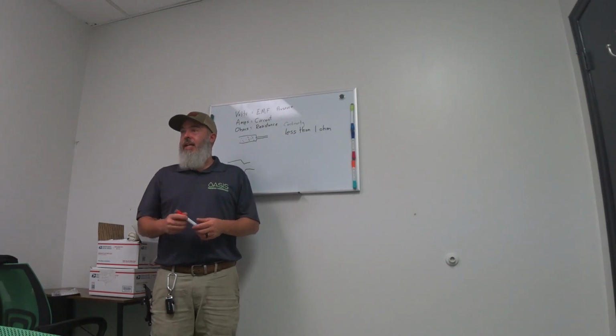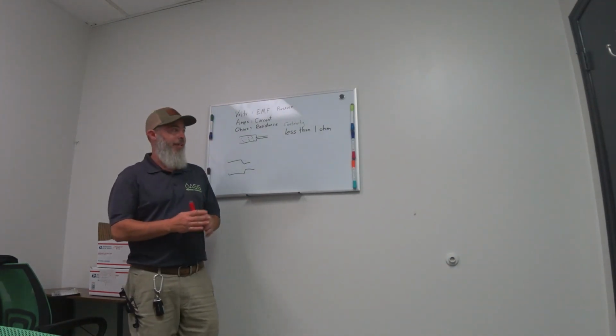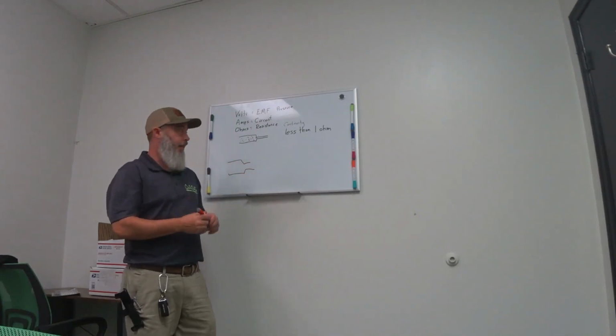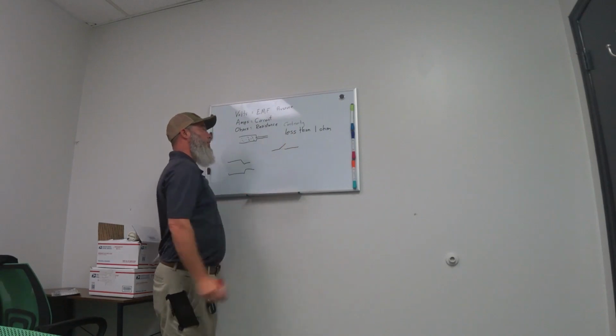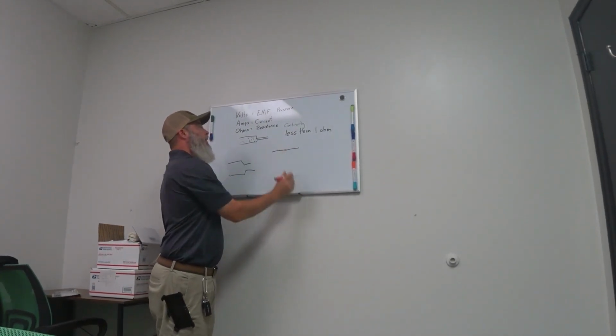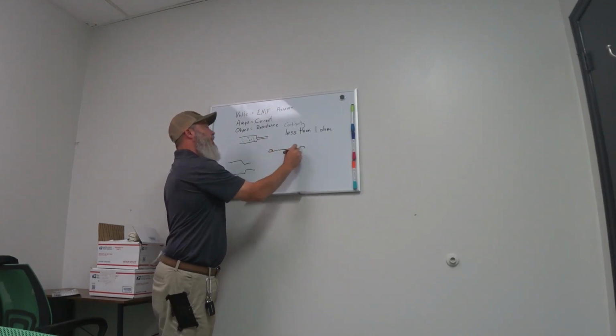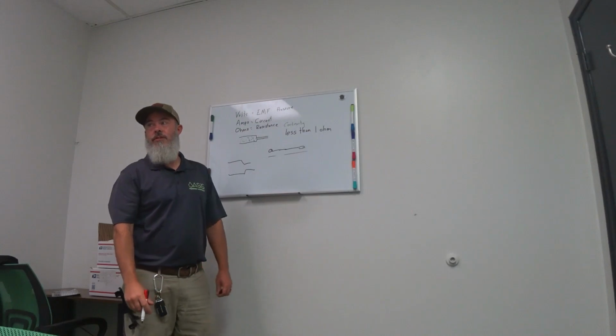There's thermostatic, there's mechanical. Let's just take a mechanical bin control. It has a flap, and basically the flap is just a switch. So once that flap is closed, from this point to this point, you have continuity. Less than an ohm.